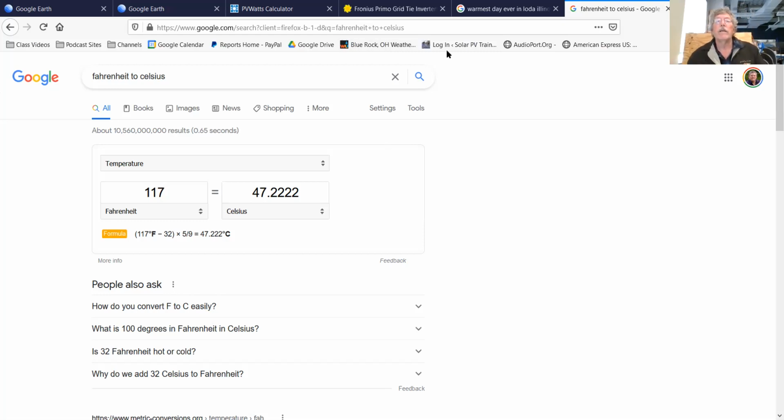So I'm going to jump in here and I'm going to go ahead and go back to my whiteboard. And I take the delta. So for the coldest day, minus 38. 25 is standard test conditions. The difference, or the delta, is going to be 38, which is negative, plus 25. So that's 63 degrees Celsius. So that's our delta, the difference between minus 38 and positive 25.